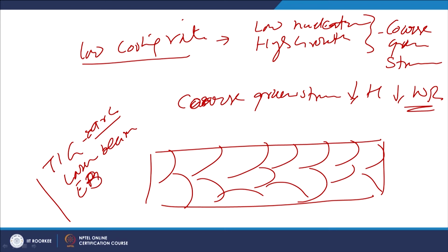These are comparatively high energy heat sources as compared to other manufacturing processes, which may lead to a lower cooling rate. So, if a laser is applied over a small area, leading to a higher energy density, a very thin layer of the component up to a certain depth will be brought to the molten state.